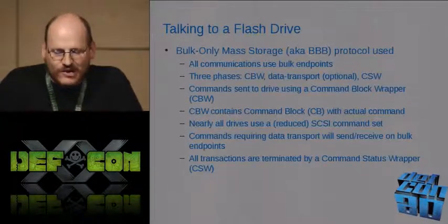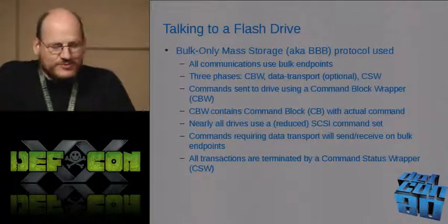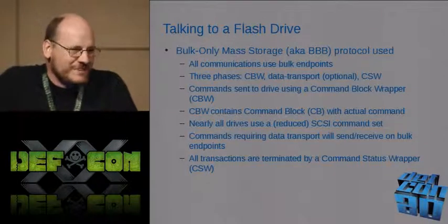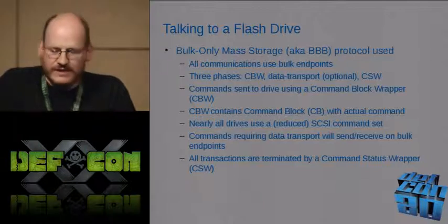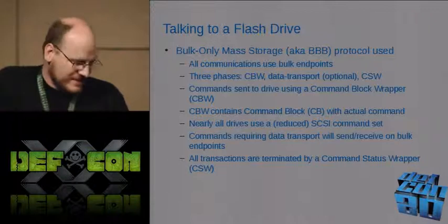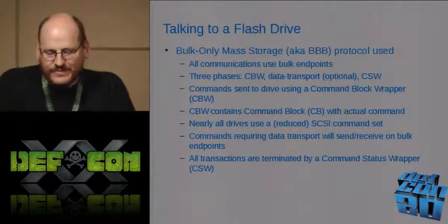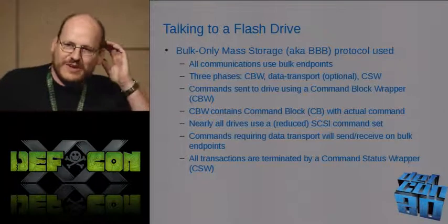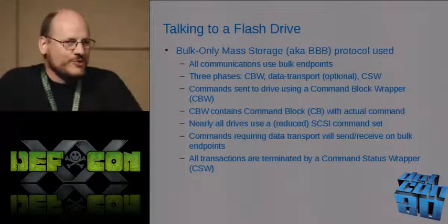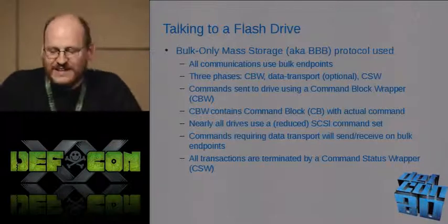All right, so how do you talk to this flash drive anyway? You have this bulk-only mass storage protocol. Sometimes it's called BBB because it's all bulk. And unlike many devices, instead of using the control endpoints, you use the bulk endpoints. And there are 3 phases. There's a command block wrapper phase, where you send a command block in a wrapper.